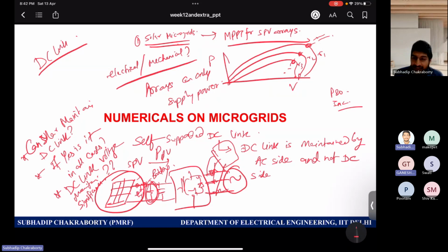Again, one question I want to ask you: do wind generators absorb power or only deliver power? We can also use a normal synchronous generator, sir. Yes, all are possible. But you have to apply proper control to make them rotate at the speed which delivers the maximum power. You need to have the concept very clear in your mind that the speed of the turbine and the speed of the generator do not have any relation. Your wind will try to rotate whom?